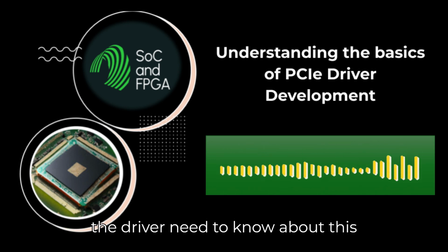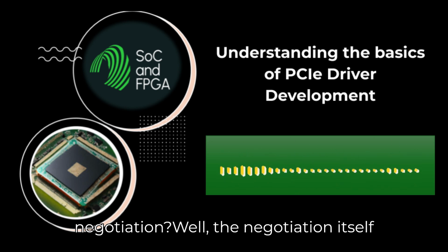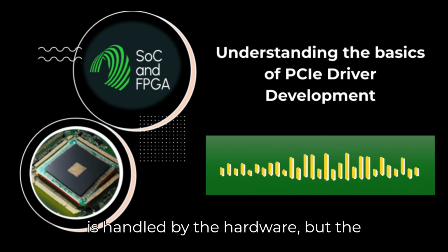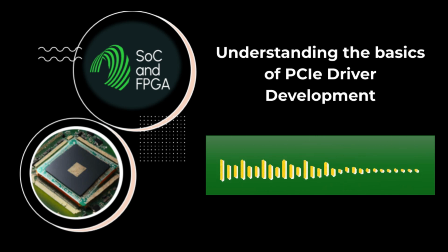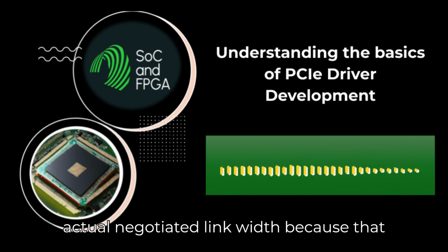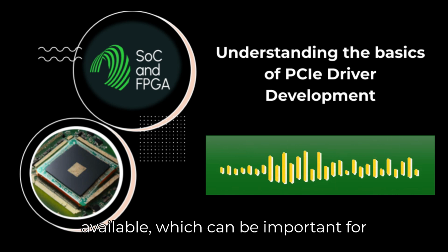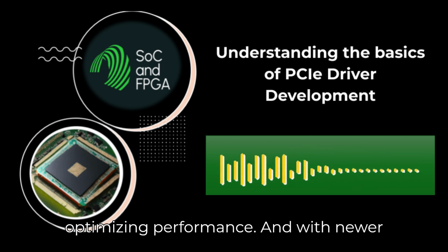Does the driver need to know about this negotiation? Well, the negotiation itself is handled by the hardware, but the driver does need to be aware of the actual negotiated link width because that determines the maximum bandwidth available, which can be important for optimizing performance.